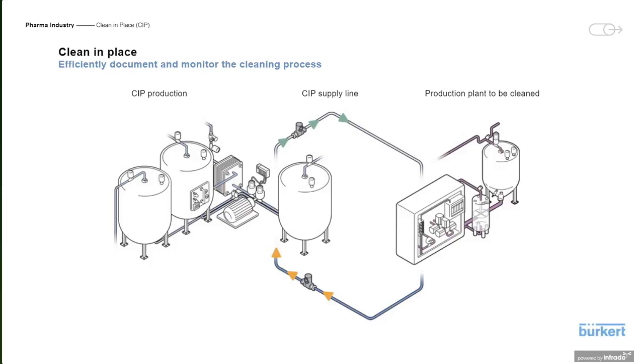I'd like to hit a few of those and lay the groundwork for how FlowWave would function based on the process steps of CIP. You've got your pre-rinse to drain. After that, you've got a caustic soda wash. One thing with FlowWave, it's very good at detecting minute changes in what I'm going to call concentration.